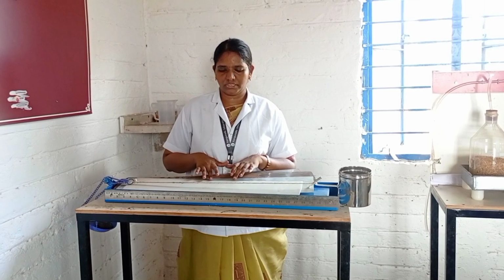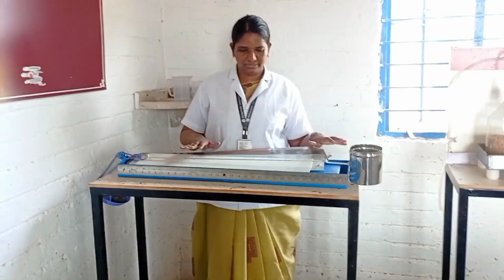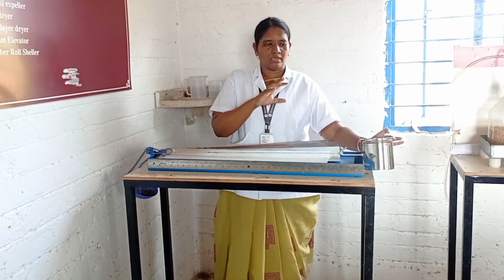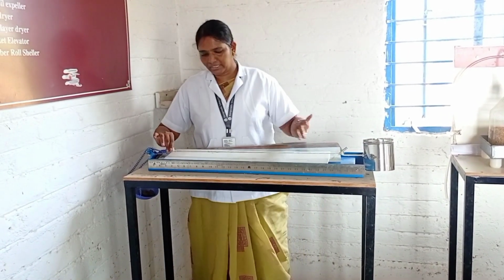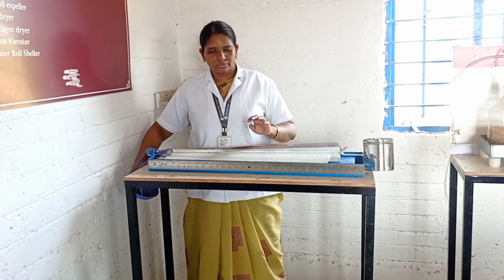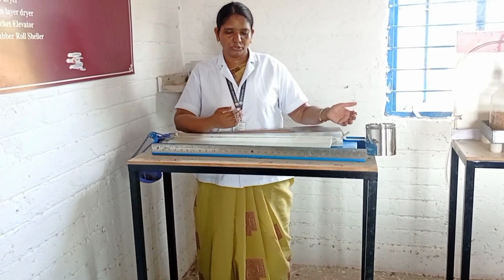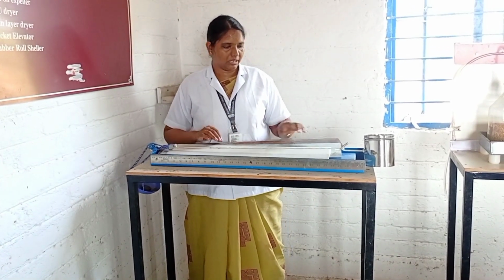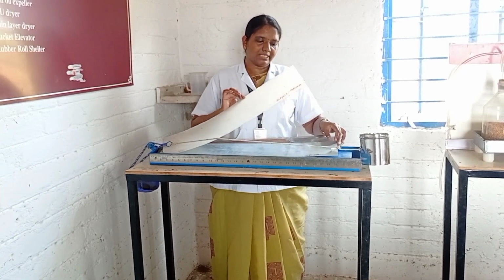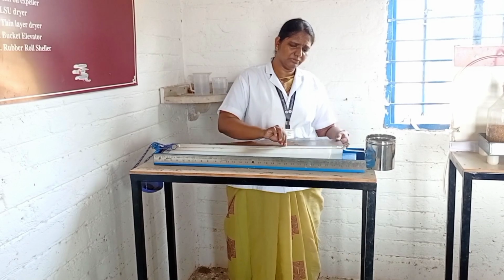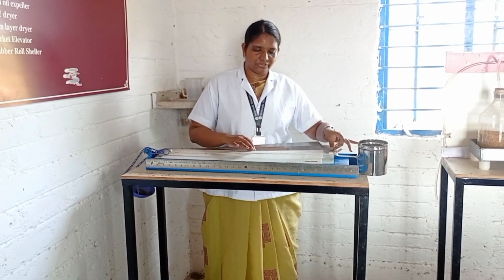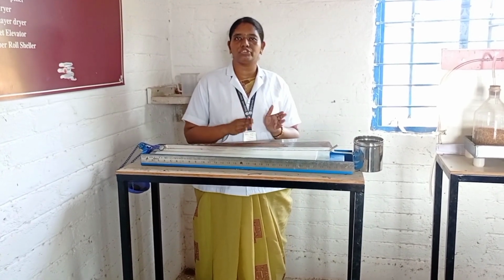For the coefficient of friction, we are going to use this apparatus. It consists of a container where we can pour grains at a particular weight, and then it consists of a pulley. Here we have to add a certain amount of weight, from which it starts to move from one area to another area. Here we are going to use 4 different kinds of material. One is acrylic, second one is iron, third one is copper, and final one is stainless steel. For these 4 different surfaces, we are going to find the coefficient of friction.